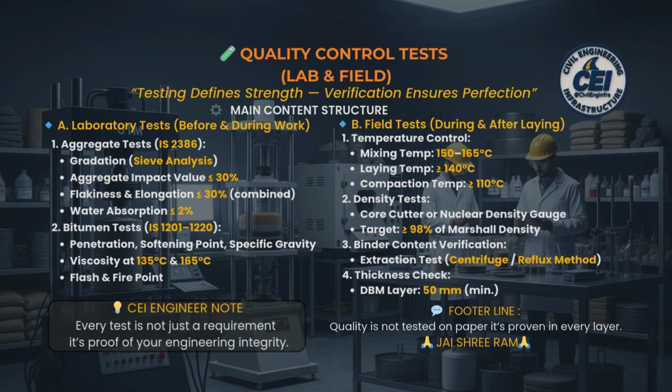Thickness, 50 mm minimum. References: MoRTH Section 507, IRC 111, 2009, IS 2386, IS 1201-1220. Quality is proven through every test, and every test is a new lesson.